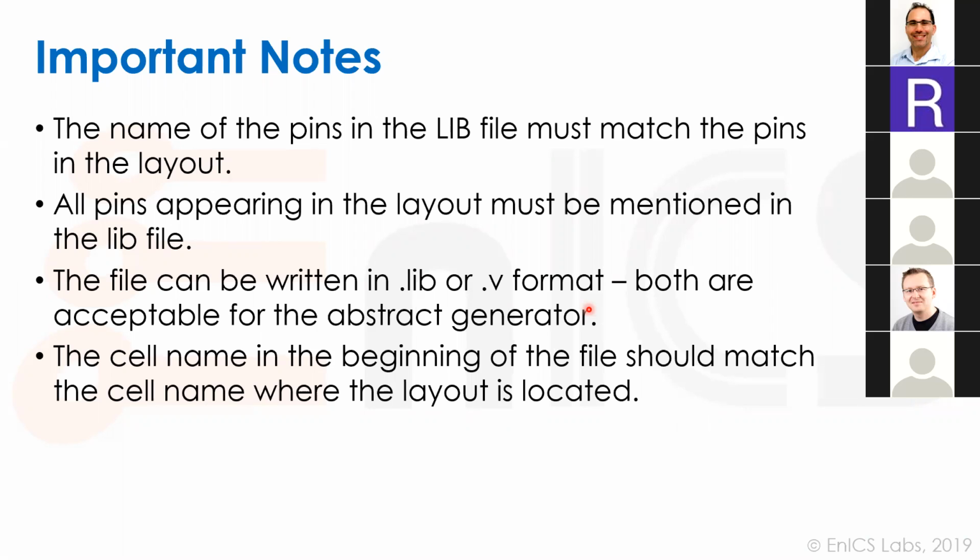And the file can also be written in a .lib version or a Verilog file. Both are fine. We just write it in the lib. And you need to make sure that the cell in Virtuoso, the cell name and the library name appear exactly as they should in the lib file.